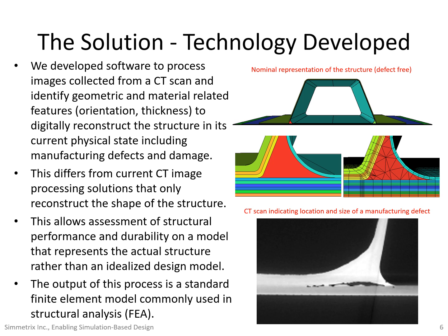Now, let us provide some details related to this technology. The current durability assessment modeling process uses an as-designed representation of the asset, which does not represent the physical condition of the asset, and this could lead to erroneous MRB decisions. The recent advancements in industry using computed tomography make it now possible to non-destructively identify the state of the asset by disclosing manufacturing defects or deviations from the nominal design, and deformations and damage induced due to operation of the asset. The digital reconstruction of the asset from the set of images that result from computed tomography measurement enables us to create an accurate individual representation of the asset in the computational domain.